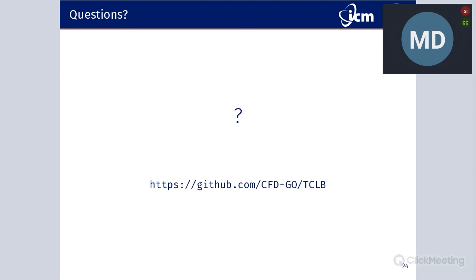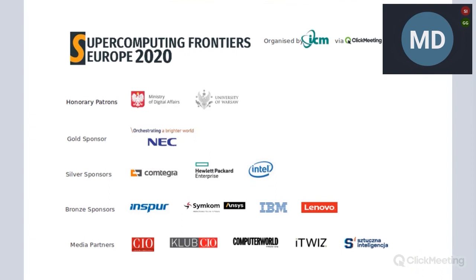Our solver is capable of optimization, so that's the adjoint part. We could generate the direct code and the adjoint part. This is discrete adjoint, and it can be used directly for optimization, for example drag optimization or heat transfer optimization. So the adjoint is sort of an extra to the code. It's not part of the numerical optimization.